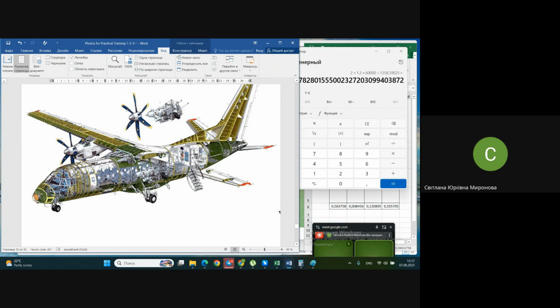In this torsion box structure, you have rather thick metal skin supported with stringers, and this skin with stringers together helps the spars to resist the bending moment. Approximately half of all the loads due to bending moments will be taken by spars, and around half by these so-called working skins or working panels.